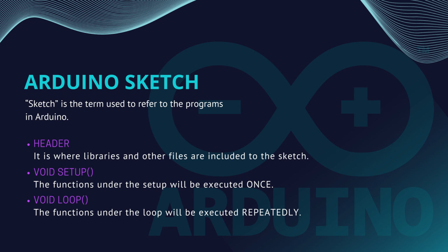It is followed by the setup part, or presented as void setup. The codes under this area are executed once. It is where initialization, categorizing pins, and telling the microcontroller what is to be executed once upon boot up.